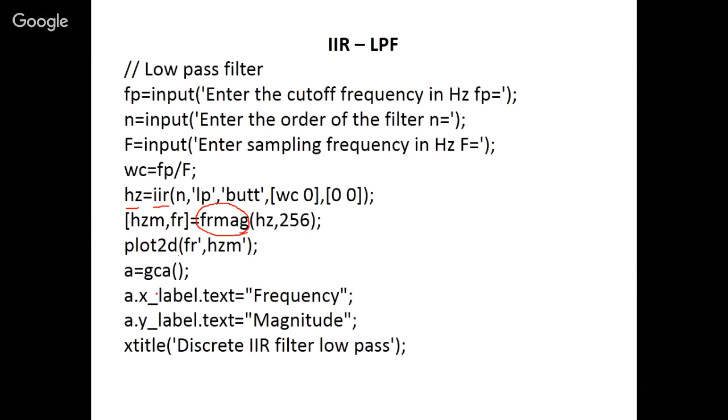So we have learnt in filter what is the common design of the filter, that is a simple filter command with the numerator, denominator, and the input signal. After that we have found out how to design an FIR filter with the help of the WFIR command, and how to design an IIR filter of low pass with the help of the IIR command. Instead of LP, you can use HP, you can use BP, we can use SB, and all these things you can practice yourself.